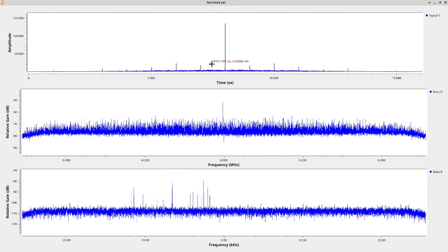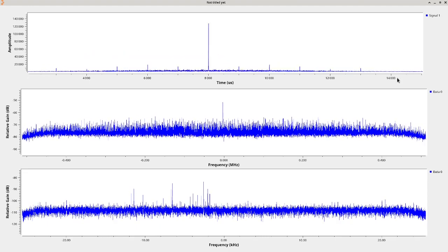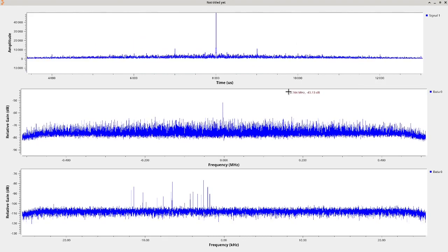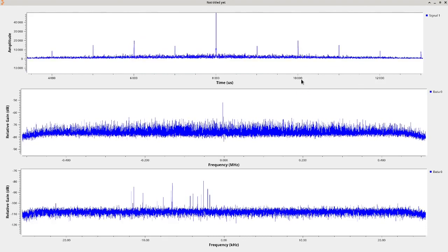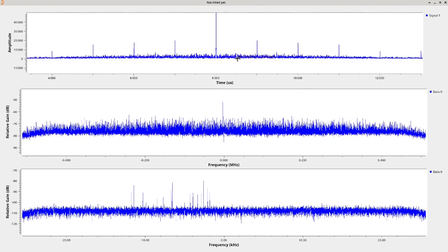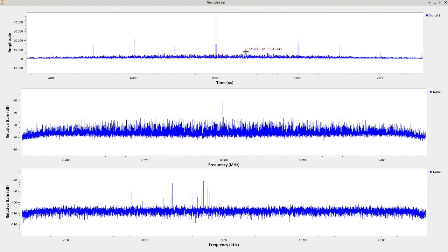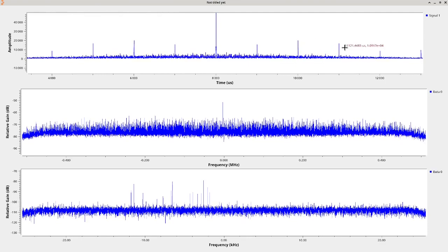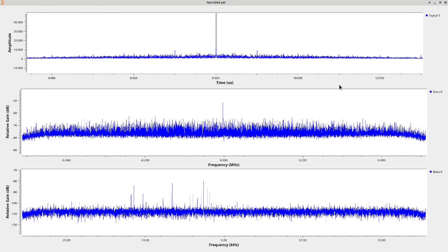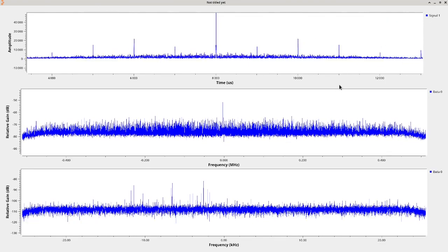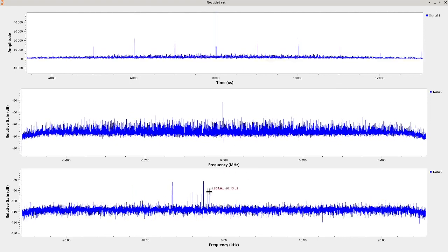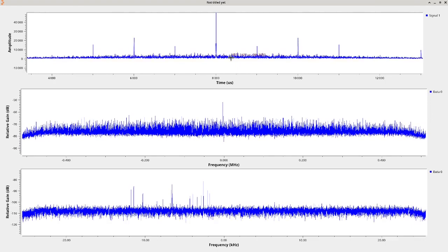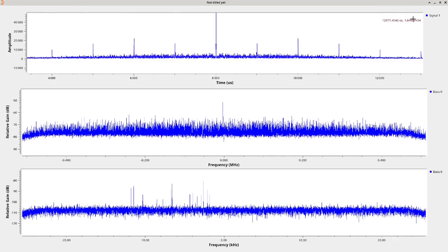And by looking at the autocorrelation, we see here the peaks that repeat once every millisecond. So we have 8,000, 9,000, 10,000. So every millisecond, the autocorrelation peak repeats. So this demonstrates various techniques for detecting spread spectrum information, either by taking the nth power of an NPSK signal or by autocorrelating, as long as the code repeats periodically.